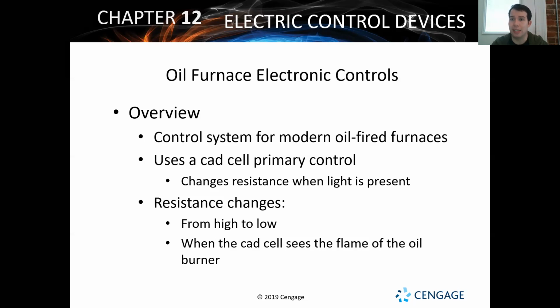You can actually measure and test a CAD cell with the light from any kind of light. The easiest way to do it is it's going to have 2 leads to it, all right? And you can actually see if you cover up that CAD cell, and you put your leads from your meter into the 2 wires going in and out of that CAD cell, you will see resistance build up. You'll see it go higher and higher and higher. But then you take your thumb off and you uncover that CAD cell and you put it towards a light, or you put like a flashlight right over it, and you'll see that resistance drop quickly because it's reacting to light. And that's a way to test a CAD cell.